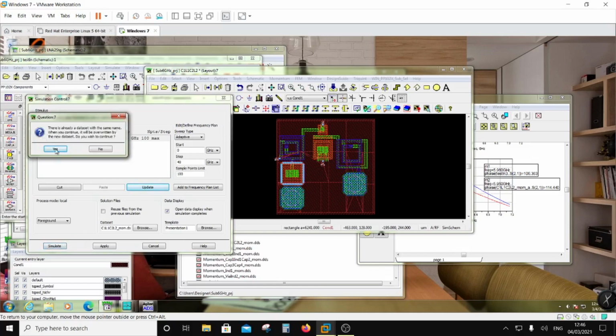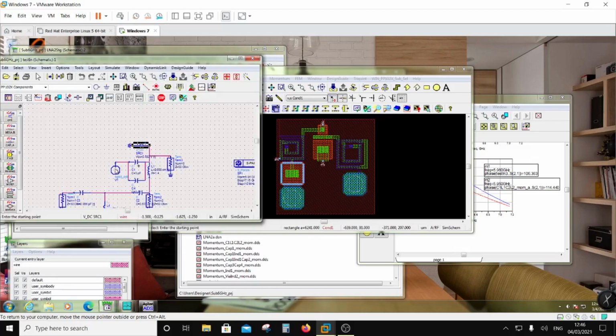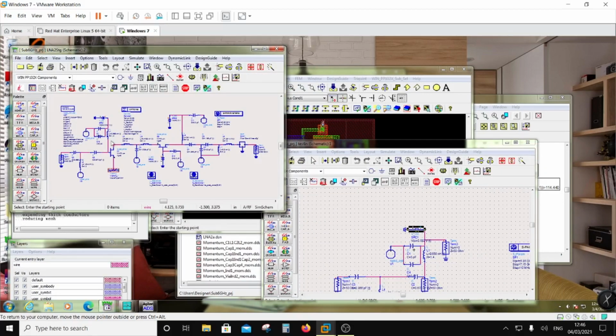So once the simulation is over, I'm going to generate a lookalike of this and place that lookalike in my circuit simulation over here. And once I have done that, the performance will slightly move, and then I would use the other components to get back my performance. So I will proceed from input to output in the same fashion. After that, I'm going to do an interstage match. And once the interstage is done, then I will proceed to the output. So this is done.